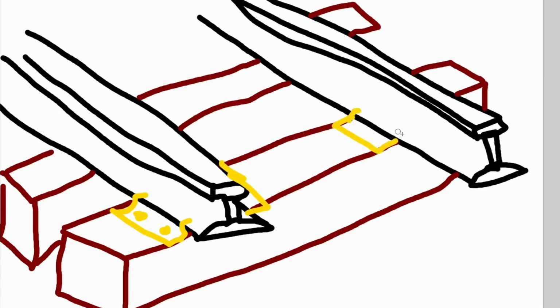It allows for a much stronger bond between the tie and the rail itself. It also gives a greater bearing surface for the rail to transmit its force through the foot of the rail and then through the large tie plate down to the tie. And it also helps reduce some of the wear in the tie itself. So you typically have tie plates, and then the spikes are driven in, and that makes for a more robust system.